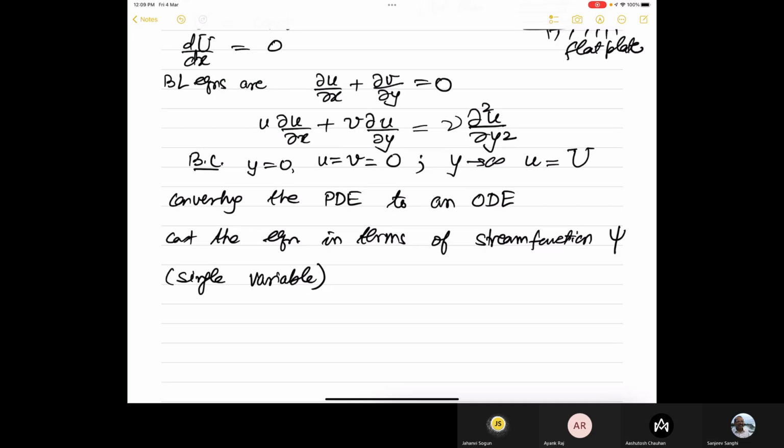Any answers? I think yes, it will exist. Why? For 2D flow, the stream function exists even though the flow is rotational. If it were irrotational, then a velocity potential phi would exist. Only phi will not exist in the boundary layer because the flow is not potential flow.